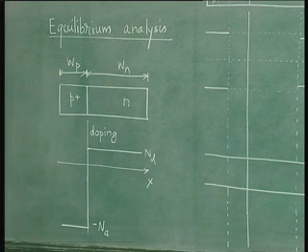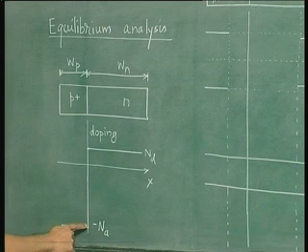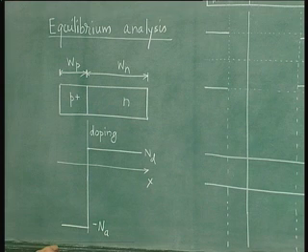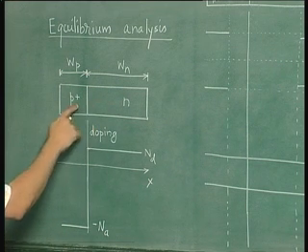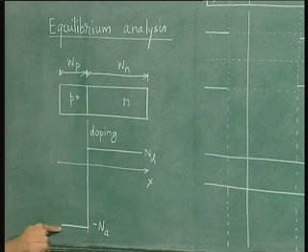the respective regions. Then we have made the abrupt junction approximation, which means that the doping changes abruptly from the P side to the N side. And then we have assumed that these two regions are uniformly doped. So the doping is constant in these two regions.